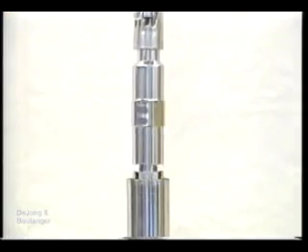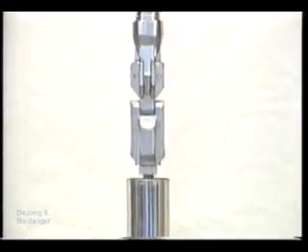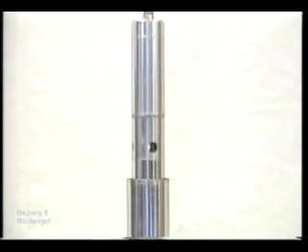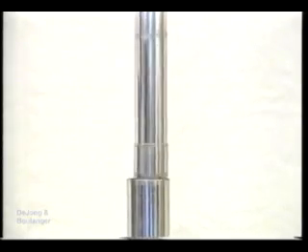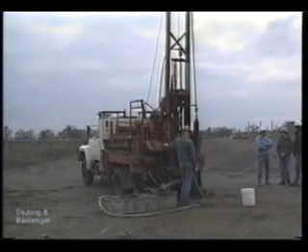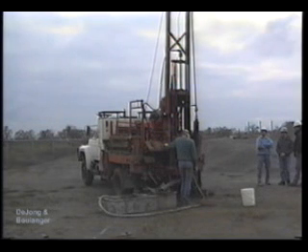Wireline retrieval systems expedite coring by removing only the full inner barrel from the hole, thus retrieving the sample while leaving the outer barrel and drill rods down the hole. The type of coring equipment and operating procedures can greatly affect the quality of the retrieved rock cores.